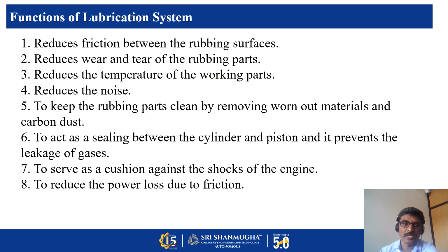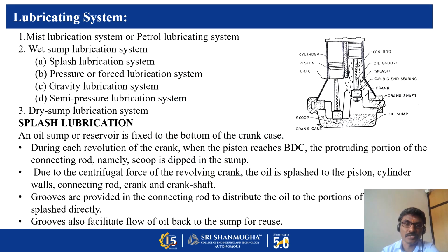And the functions of lubrication systems are: reduces friction between the rubbing surfaces, reduces wear and tear of the rubbing parts, reduces the temperature of the working parts, reduces the noise. To keep the rubbing parts clean by removing worn out materials and carbon dust, to act as a seal between the cylinder and piston, it prevents the leakage of gases, to serve as a cushion against the shocks of the engine, and to reduce the power lost due to friction. So these are the various functions of lubrication system.